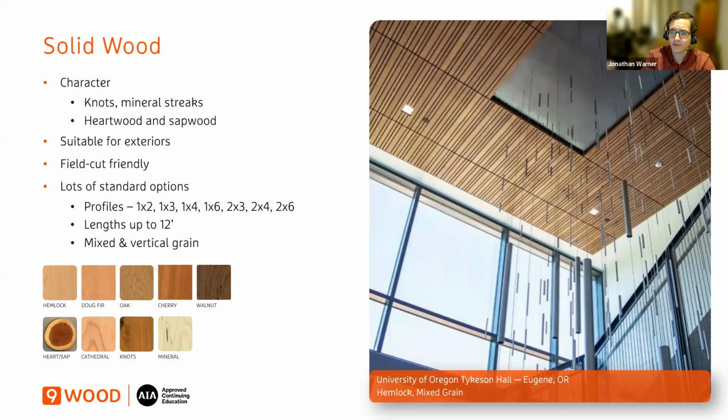Solid is field cut friendly. It's suitable for exteriors and it has a lot of standard options. You've got a lot of different profile sizes from 1x2 to 2x6, lengths up to 12 feet, and you can have mixed and vertical grain. So there are a lot of different options with solid. Just be aware of the color and character variation you're getting into when you specify a particular species.